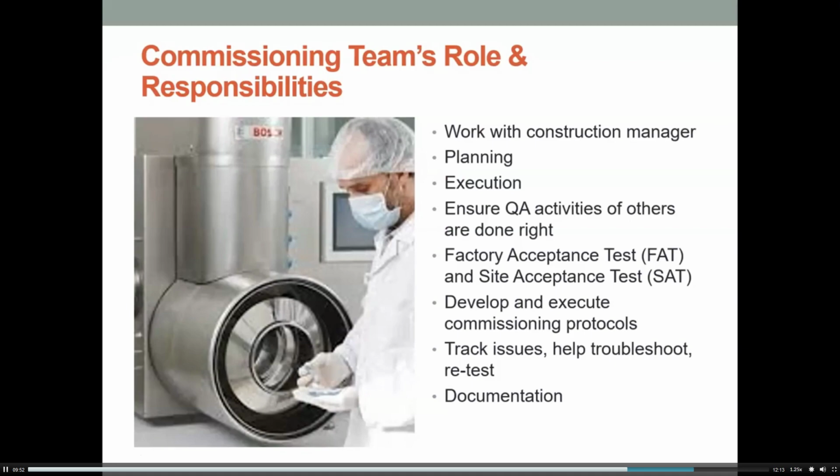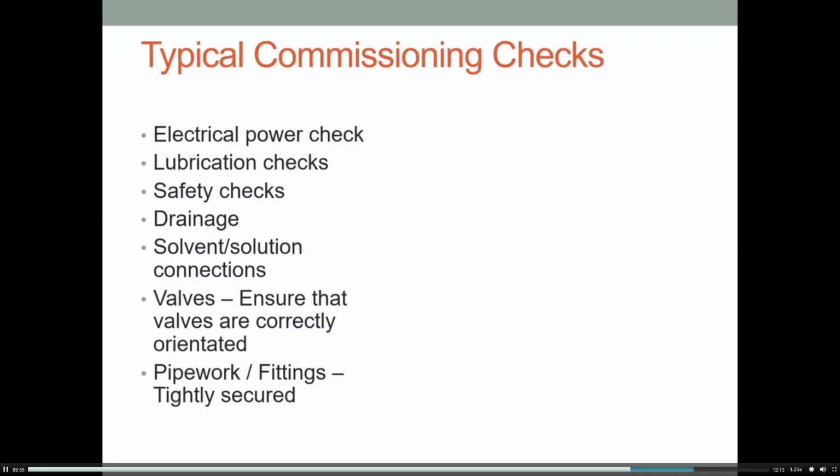Complete any documentation that's required. Typical commissioning checks might be things like making sure your electrical power is working, checking that your lubrication is okay, and knowing where you need to maintain that. Safety checks: making sure your emergency stops and any other safety requirements are adhered to. Making sure that you're looking after drainage. Do you need to have wastewater? Where does it need to be processed to? Etc.